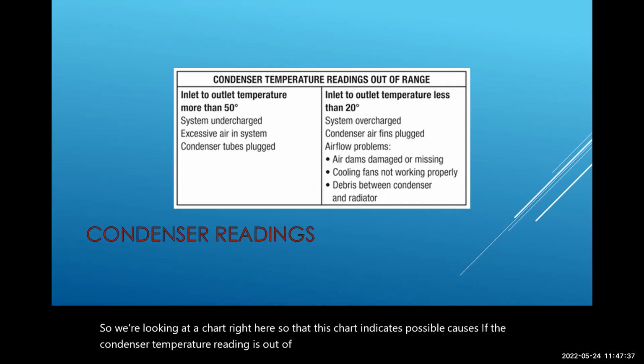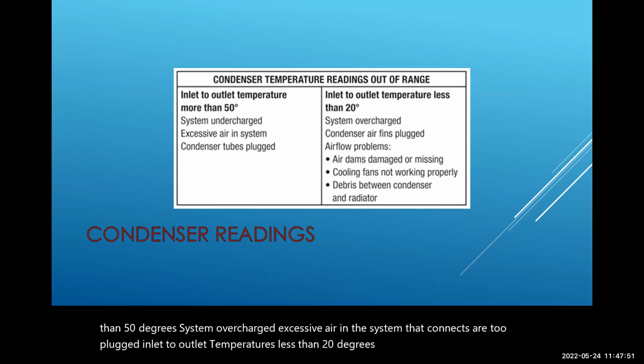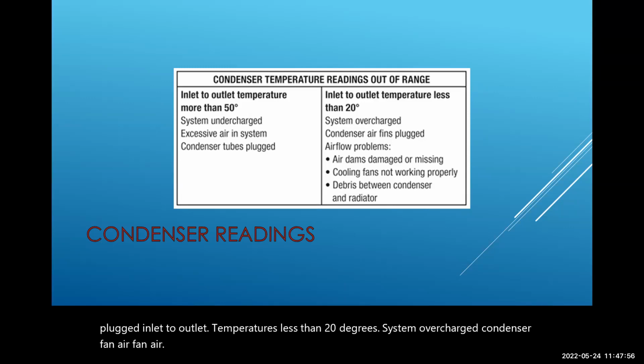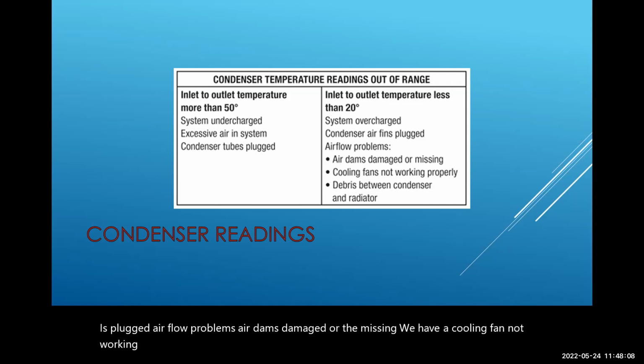Inlet to outlet temperature more than 50 degrees: system overcharged, excessive air in the system, the condenser tubes plugged. Inlet to outlet temperature less than 20 degrees: system overcharged, condenser fan or air fins plugged, airflow problems like air dams damaged or missing. We have a cooling fan not working properly, or debris between the condenser and the fan itself.